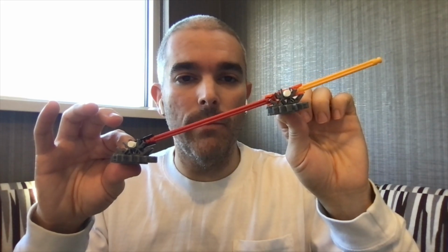In the case of point B, I'm going to take B and move it up 1. Now you can see if this is 0 and this is 1, then out at the end at point C, that's going to be 1.5. Again, that matches our influence line for the reaction By. Let's go ahead and put that on paper.